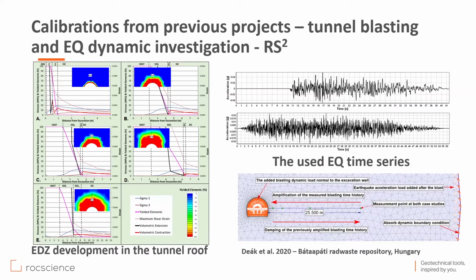You have to mention also that the damping of soils and rocks is independent of the loading frequency. By contrast, the Rayleigh damping formulation is frequency dependent and adequate to solve numerical damping. Use of Rayleigh damping in the numerical models allows the user to define the damping ratio for two threshold frequencies. The range between them has a damping ratio lower than the specified damping ratios, and frequencies outside this range are damped more heavily.